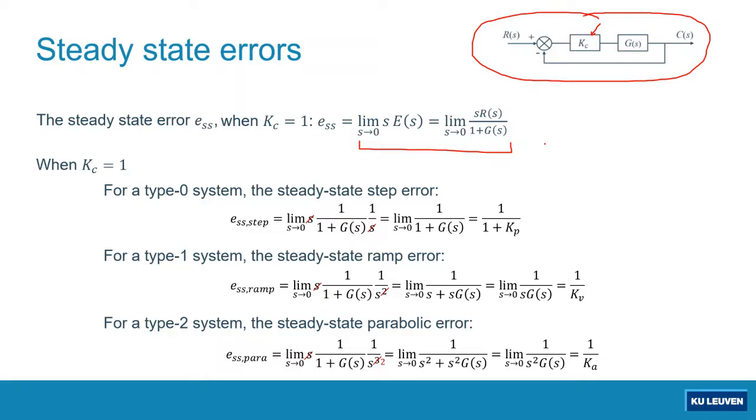We have discussed this in the previous videos. This will tell us the steady state error for a certain input R here. Depending on what the input is, we should be able to calculate the steady state error. Now to the same system, before we adjust the proportional gain Kc, consider again we have a unity feedback system, but this unity feedback system is considered as a type 0 system.